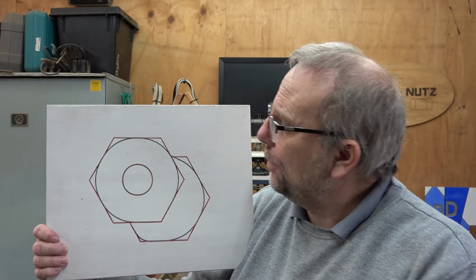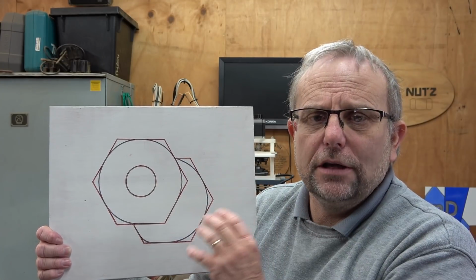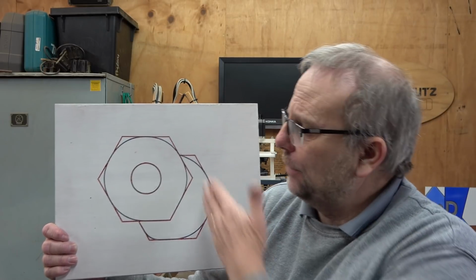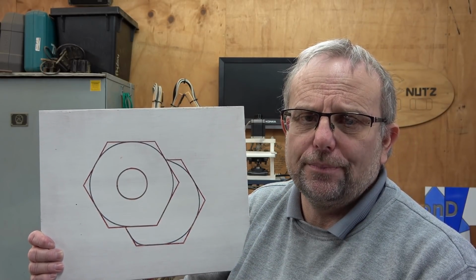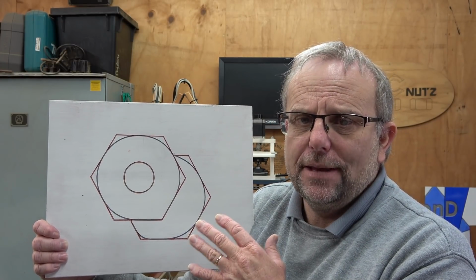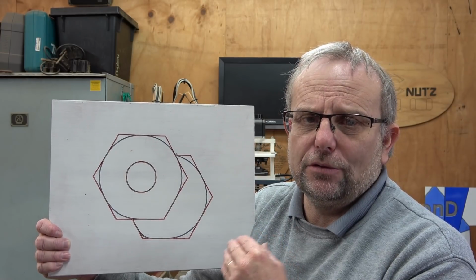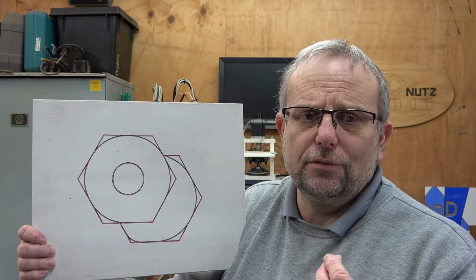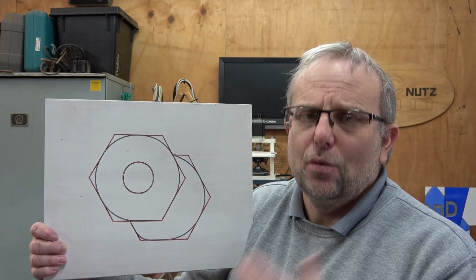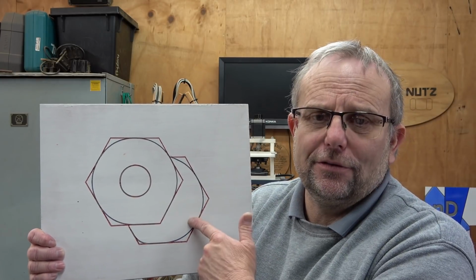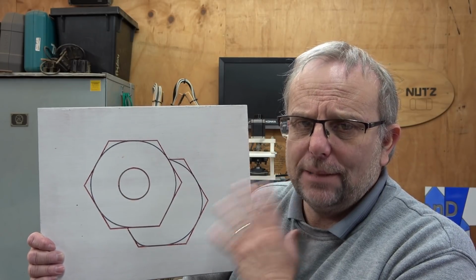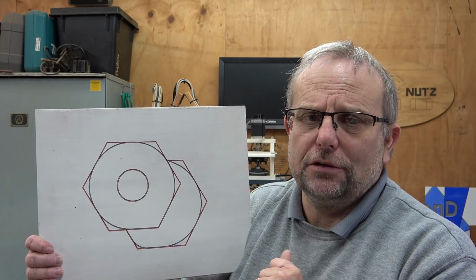Now in the last episode I showed how constant velocity can screw up your toolpaths by the simple demonstration here. My hexagonal shape basically turned into circles. That was done using default settings in Mach 3 and was done for demonstration purposes to show the effect that constant velocity has on a toolpath. Certainly when you've got it set up you will not get this bad an effect from your machine. Simply to demonstrate what constant velocity is doing.